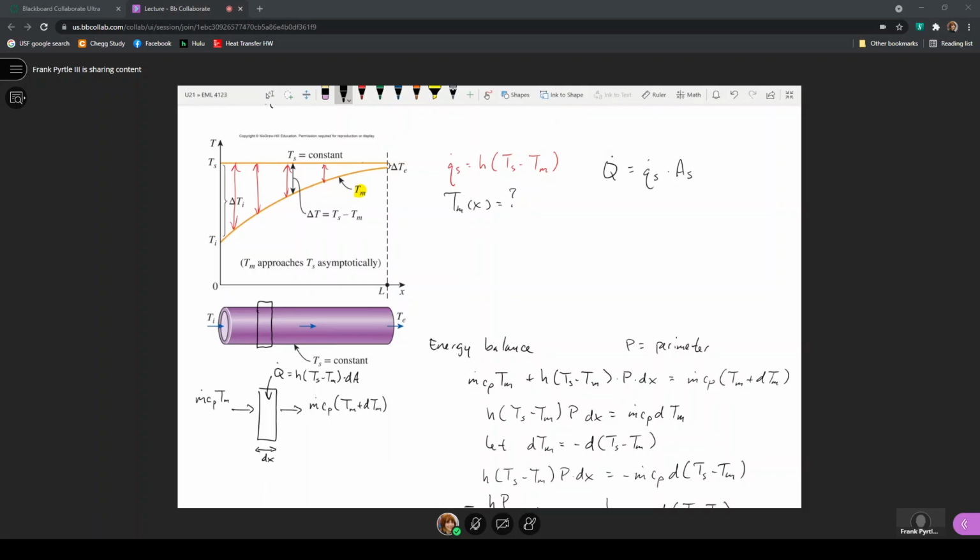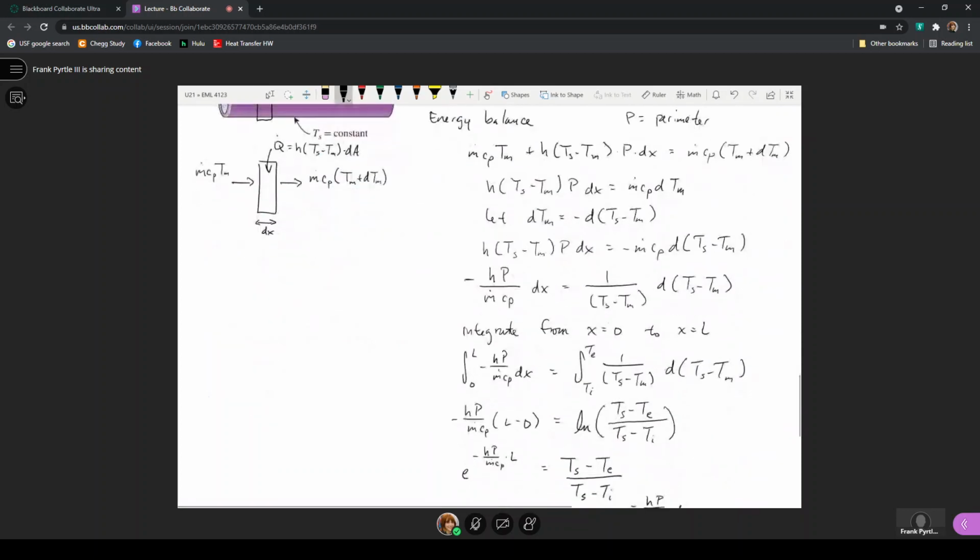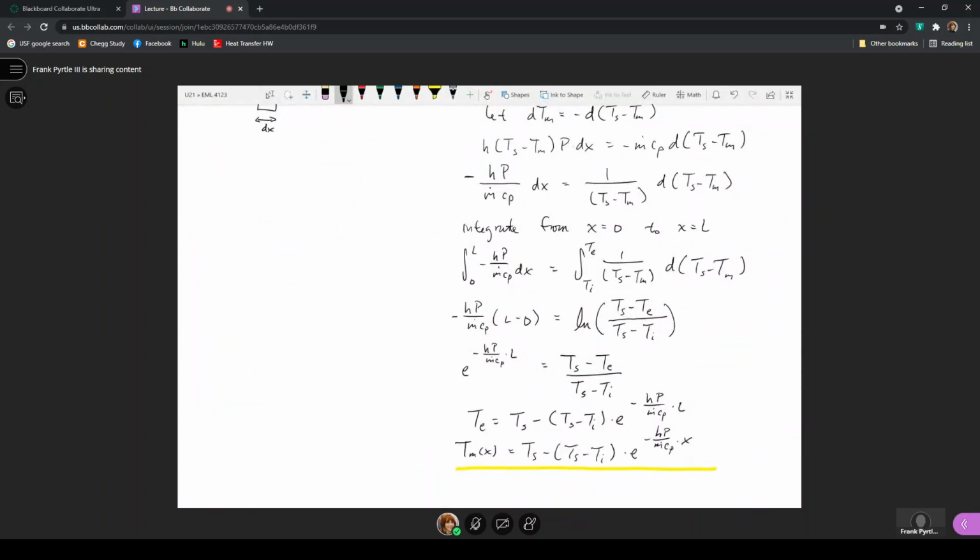Well, the surface area will be the entire inside surface of the pipe, but we know that the temperature difference between the surface and the fluid changes as we move along the length of the pipe, and the heat transfer coefficient actually locally changes along the length of the pipe until we get to the fully developed condition. So in order to write an expression for this heat transfer rate, we consider the average heat transfer coefficient, the same value used in the expression of the temperature variation of the fluid as a function of position.